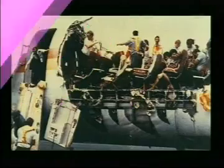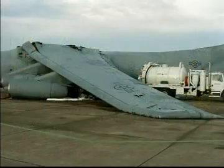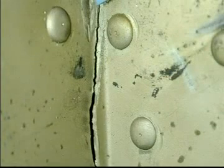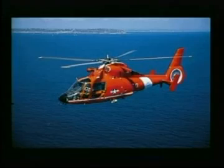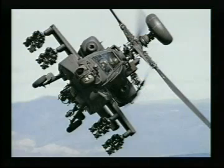Left untreated, corrosion will ultimately threaten the structural integrity of the airframe, and the results can range from expensive to catastrophic. In fact, the typical cost of repairing corrosion-related damage compared to the cost of preventing it is about 100 to 1. For this reason, aircraft manufacturers use a variety of methods to inhibit corrosion and protect the airframe after it leaves the factory and is put into service.